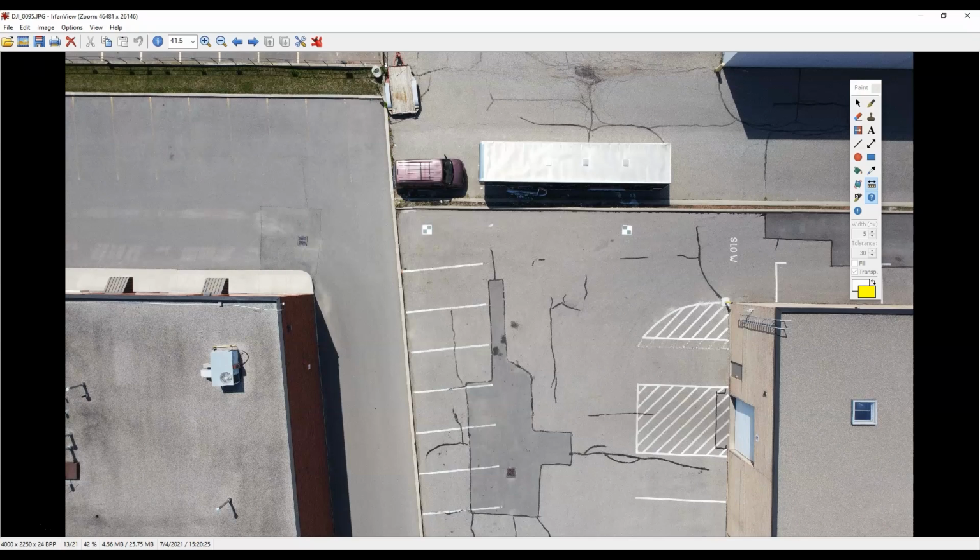So at some point, we're obviously going to be too far from this target to really make out the center well. If we double 40 meters to 80, we're probably only going to get about 20 pixels. And once we start getting up to about 120 or something like that, this target is pretty much going to disappear. It's just going to get really small and very hard to distinguish where that center point is. So for the purposes of what we did, going up to about 40 meters, maybe we could have gone to 60, would be okay using this type of target.